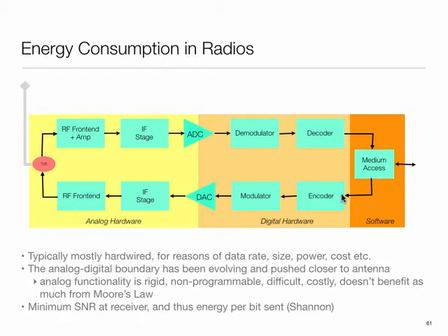You're going to take the data, you're going to encode it, you're going to modulate it into a waveform, convert it to analog, amplify the analog, and send it out over the channel, air or wire. On the receive side, you're going to do the opposite. You are going to amplify the signal, which is very tiny. You are going to change its frequency, you are going to digitize it, you are going to extract the information, and then finally the incoming bits are packetized and sent out here.